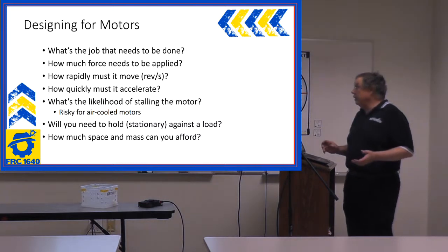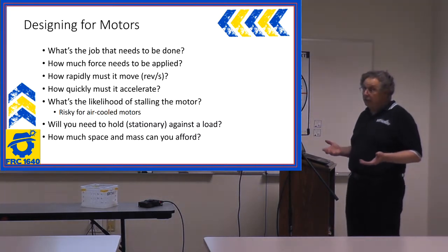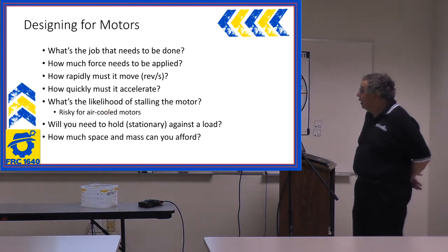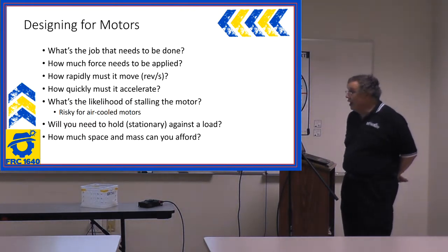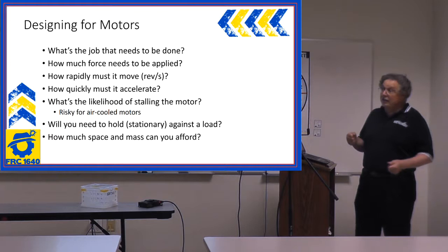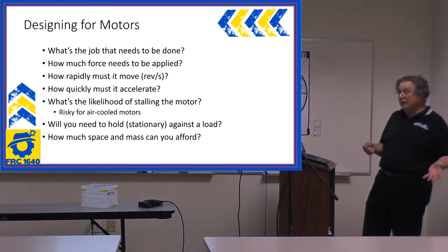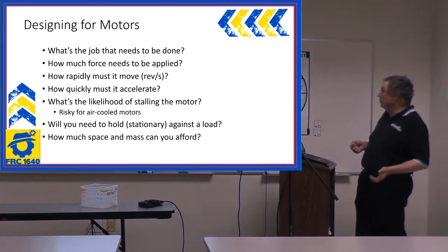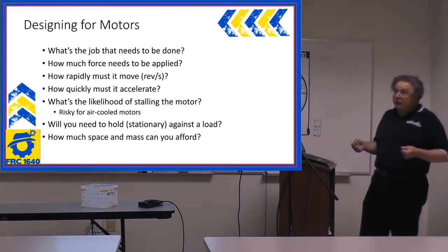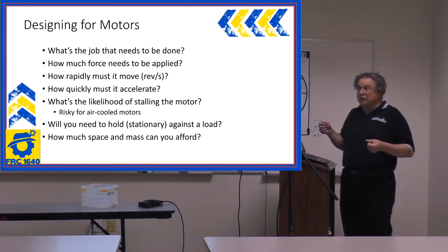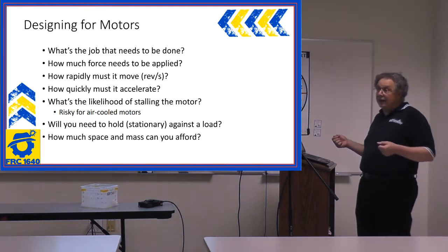You really need to know, before you pick a motor, what do you need that motor to do? What's the job? How much force does that motor need to apply to whatever mechanism it applies that force to? How rapidly do you need it to move in terms of revolutions per second?